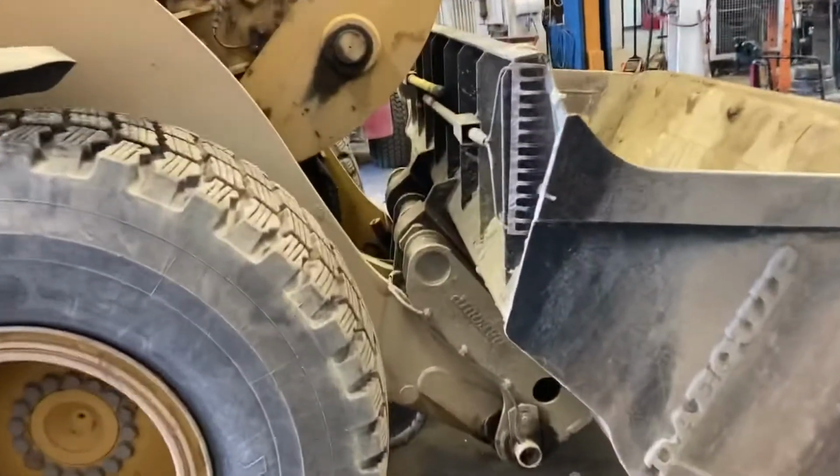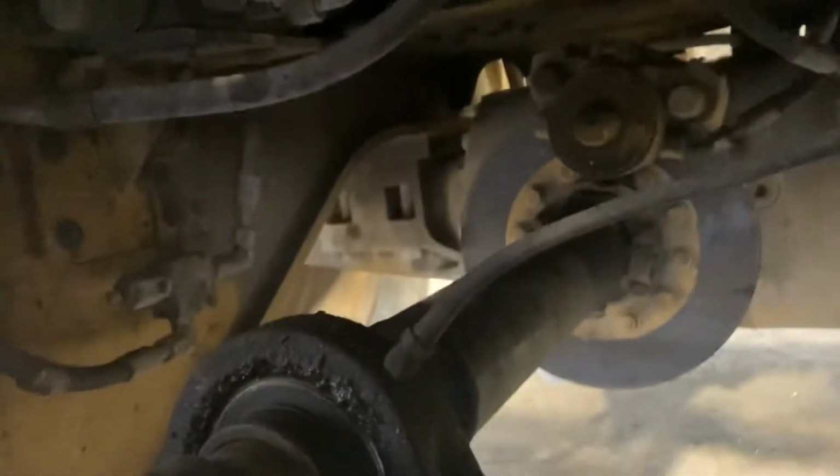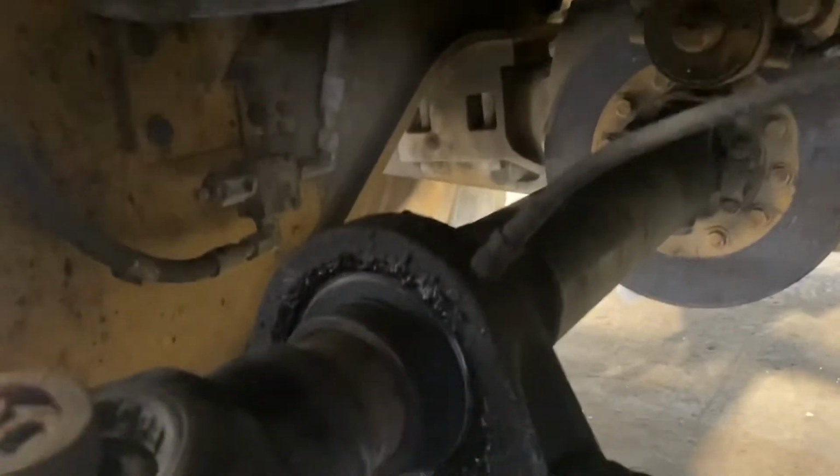So where is it located? It's located in the front of the machine. I've got the boom down now, but all you've got to do is remove this plate here. You've got to get the boom up, and then you can get a pretty straight shot in there. It's pretty easy to change. It's pretty obvious which one it is too. If you can't get the boom up, to raise the boom, you could open this. You could open that lowering valve and lift the boom with another machine or with a hoist. If not, you've got to get underneath here, and it's up in there. Let's see.